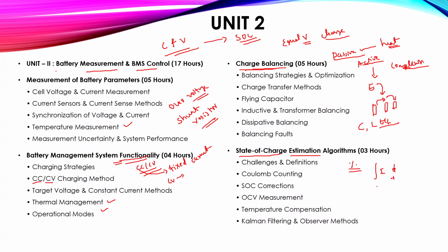However, due to the integration, error will accumulate due to sensor inaccuracies. Then another method is the open circuit voltage method, that is the OCV method, which relates the SOC to the voltage.